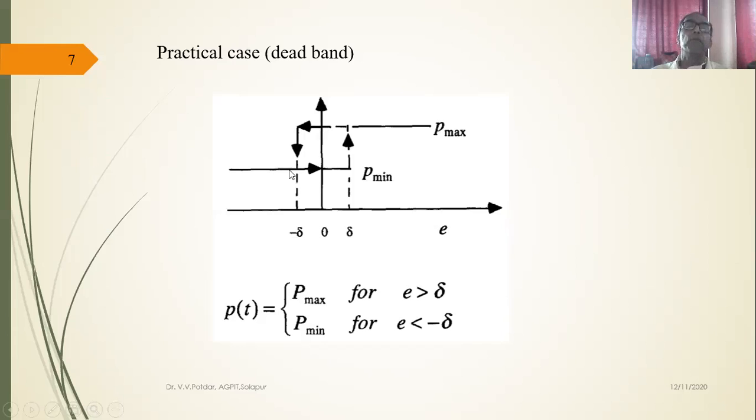Then it becomes off. So whatever this is, plus 2 degree and minus 2 degree, this 4 degree or 4 units error zone is called the dead band, because nothing is happening in between, isn't it? In this zone of 2 delta, nothing is happening. So this is called the dead zone or dead band. And then I have got the on value and off value, right?